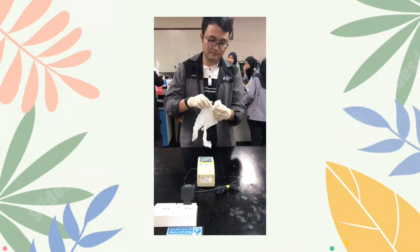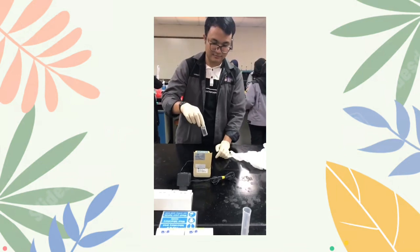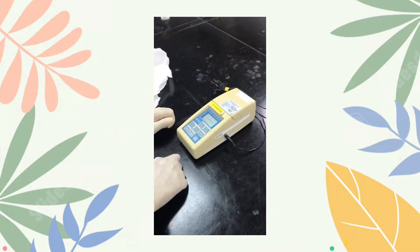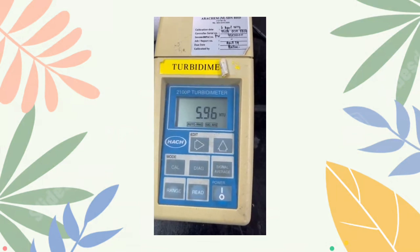Clean the turbidity bottle containing the purified water sample and use the turbidity meter to get the reading for turbidity. The result is 5.96 NTU.